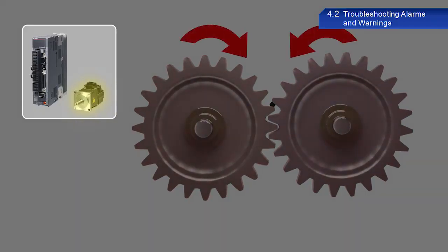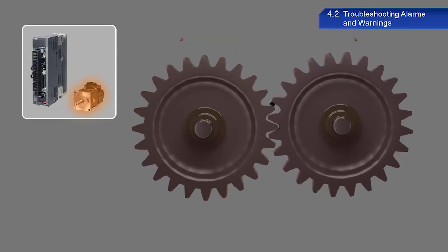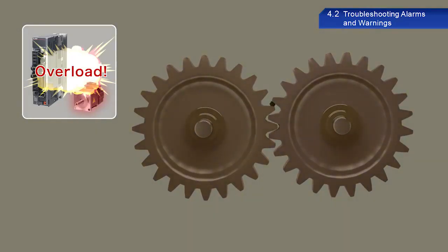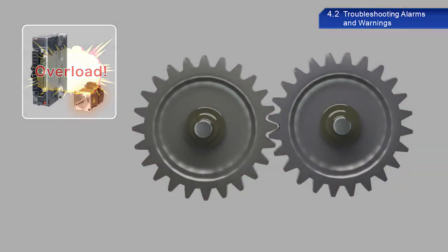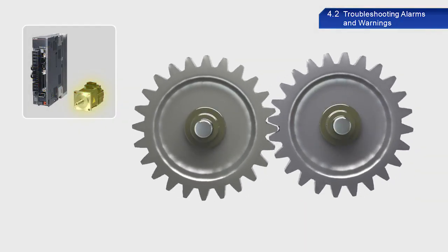Excessive current may then be output to try and move the part normally, which causes excessive load and triggers this alarm. If this happens, check mechanical parts carefully. If this alarm occurs when there are no mechanical issues, wiring may be disconnected or connected incorrectly, so check the wiring.